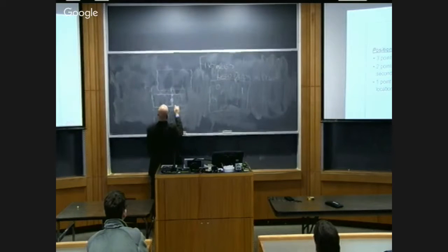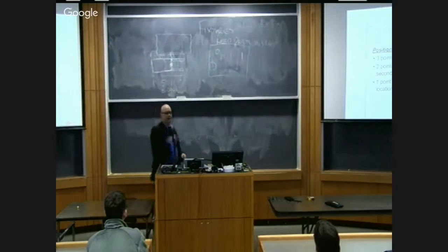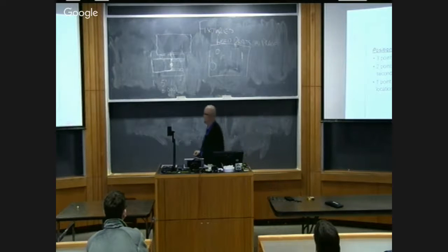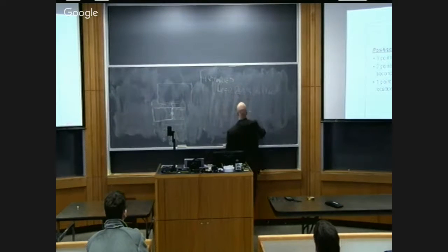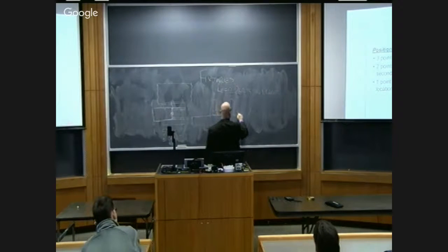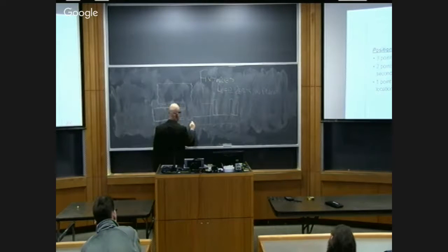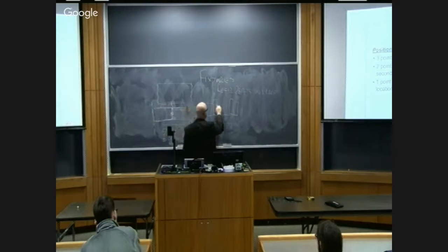I should finish drawing the picture. Yeah. So my workpiece is sitting on parallels. And so if we look at the end of a vise, you guys have seen parallels, right? You had to do something with parallels in the lab? Yeah. So if I'm looking at the end of the vise, we've got my vise jaw that sits on the bed of the vise. There's a piece here, there's a piece here, and there's the little thing that we turn, right? To give us mechanical advantage, we turn the screw. So when we put our workpiece in there, we put these little do-jobbers in that we call parallels. What's the function of the parallels?